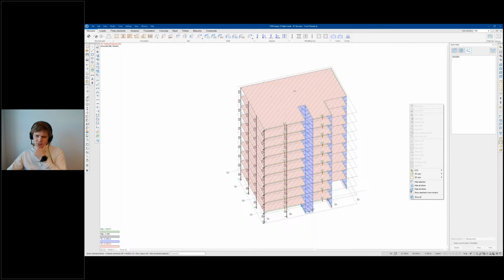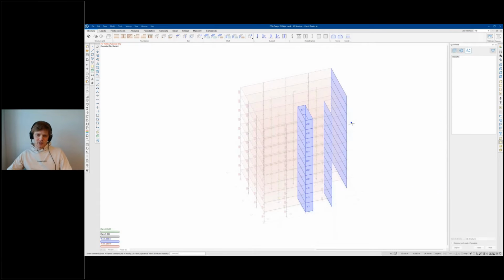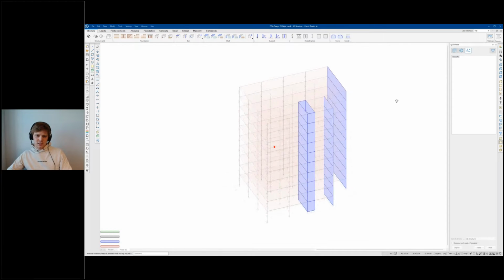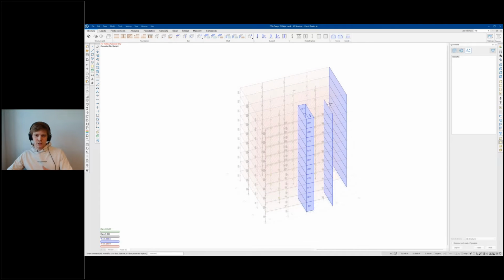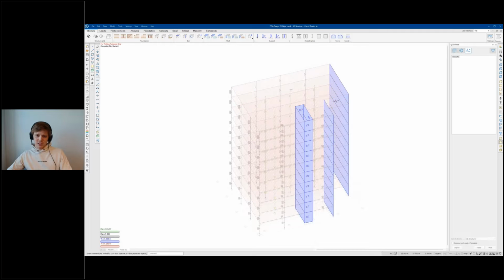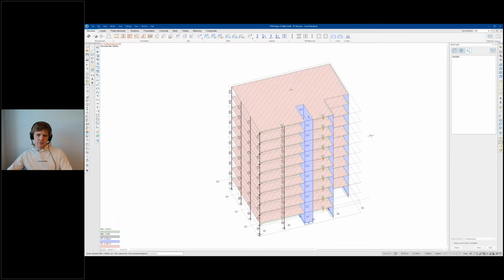Now I have an option to use something called fade all others. I click this one, and you'll see everything has been just faded. So it has set the transparency setting to an automated value, which makes it faded. And this is really nice for your documentation, also for your workflow. You can save this as a display status and then open it again. But if you want to return from this, you just click here, and it is reset display status.